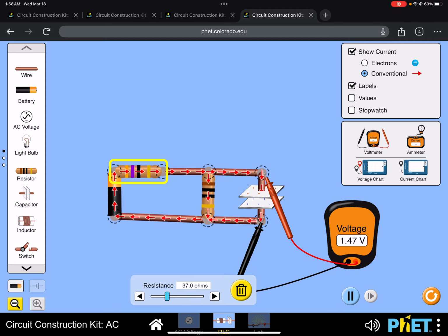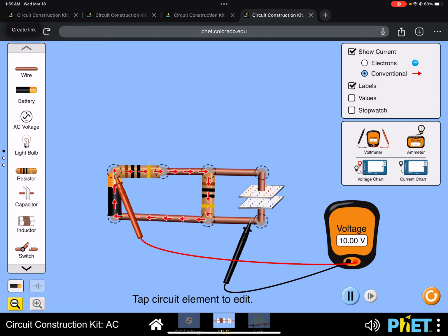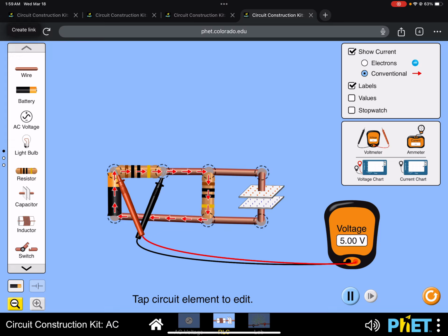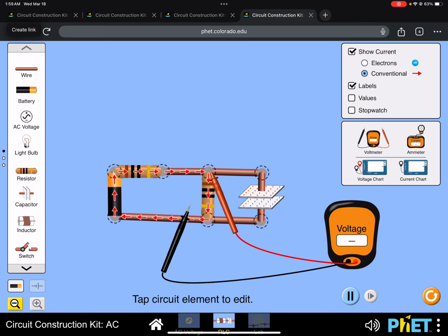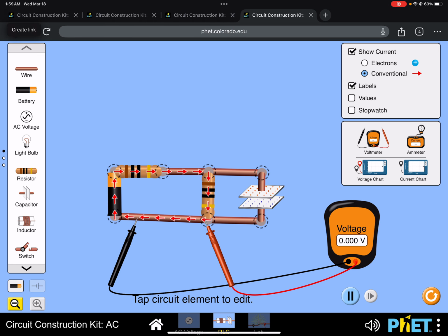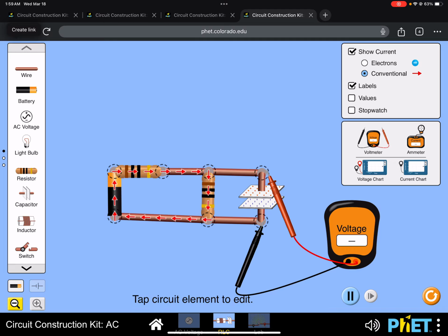And the reason for that, again, is because the potential difference of the battery, I think I made it 10 volts in this example. So the potential difference across the battery is just 10 volts, right? So the potential drop in the original resistor, I have both these resistors at 10 ohms. So it drops 5 volts, and it drops 5 volts again, all right, to reach 0 volts. And then the voltage across the capacitor is also 5 volts in this example.